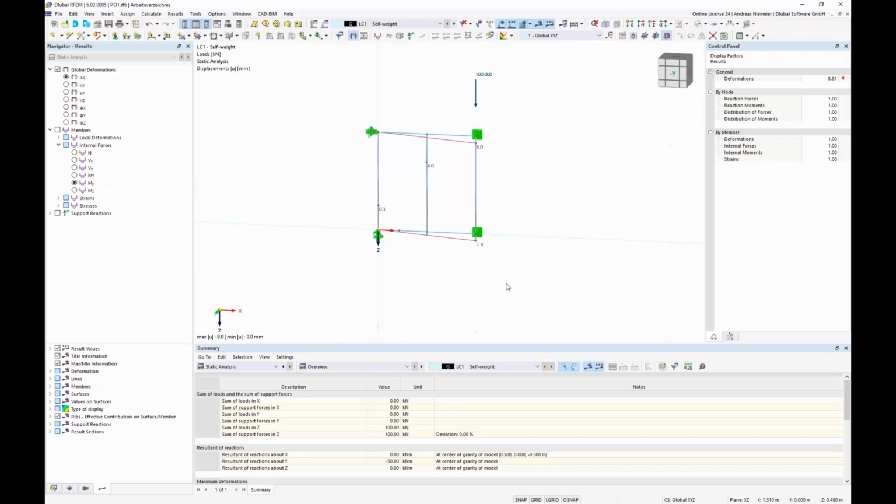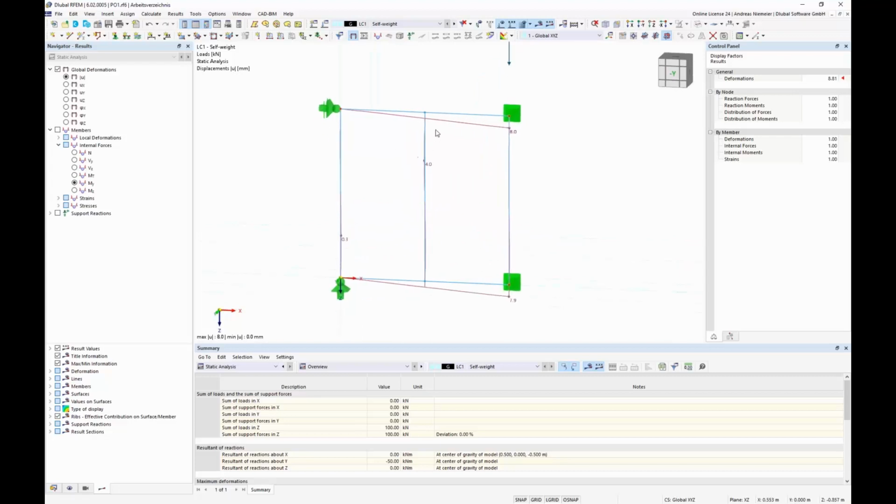But the deflection shape is still the same, and we can think about the orientation or inclination of the bracing. And I would say now this is a job for RFEM, for the computer itself, and that RFEM can find a right place for this bracing. We have to give the computer the information what it can change to find the right place. And here it's clear for us we can maybe move this node in left direction or right direction here, and even here move the node in left or right direction.